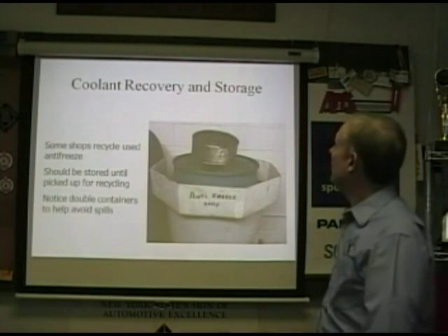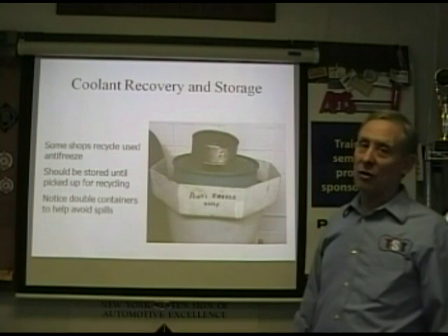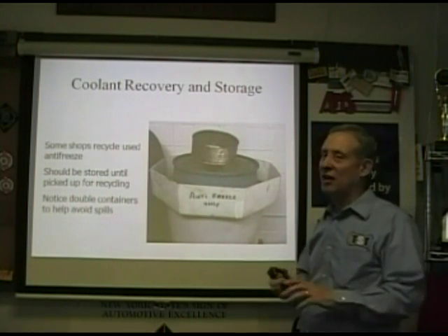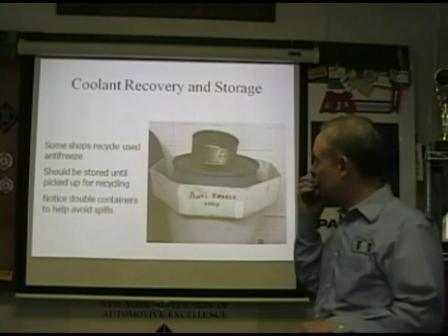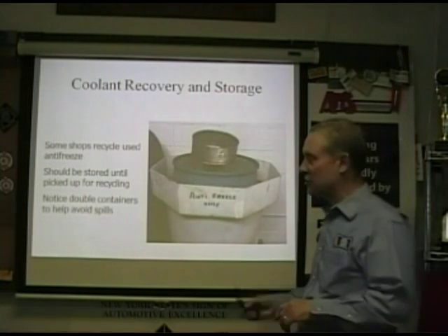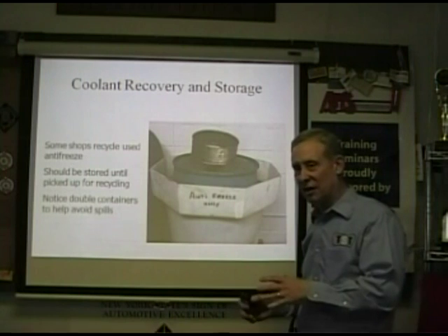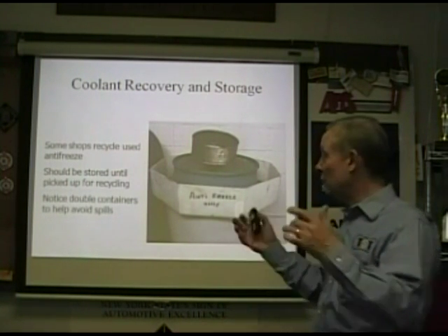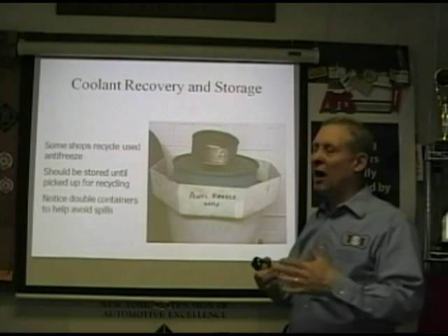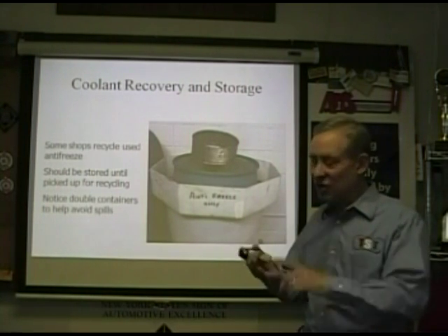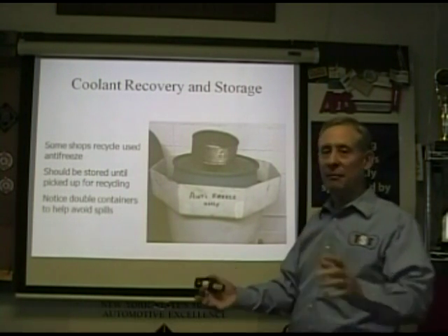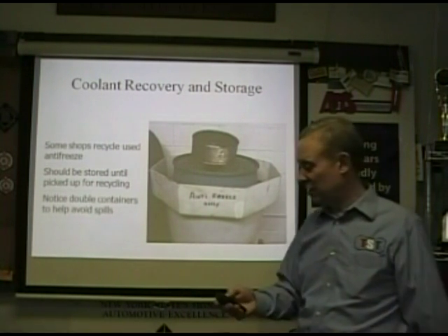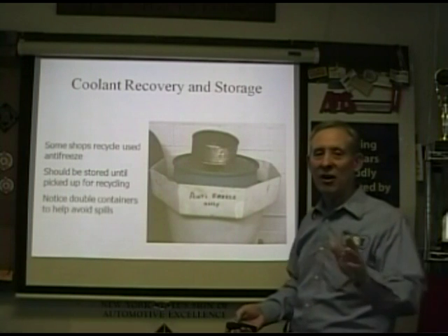All right. Coolant recovery and storage. Some shops reuse antifreeze. I've already said it. I don't like it. The only thing I ever liked to do with antifreeze was put it in the drum so it could be sent for recycling. If a manufacturer reuses the ethylene glycol, I trust their engineers and their chemistry to make it a good base product first and add their additive package. But once you're doing it in your own shop, it's very hard to have quality control.